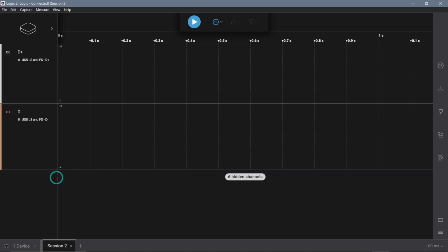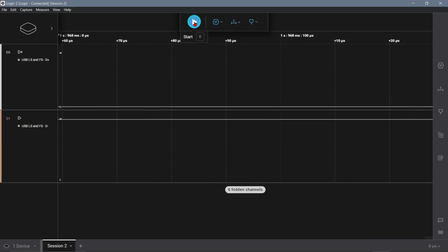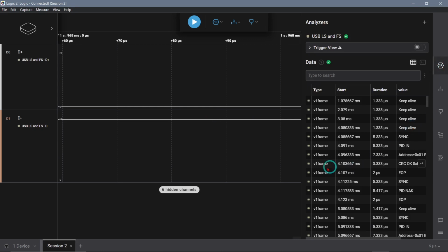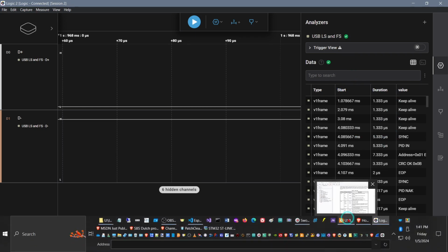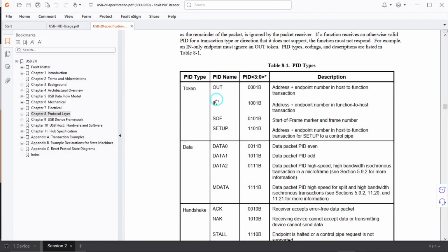And so what we're going to be doing is I'm going to hit the A key, which we know is scan code 4, and I'm going to get it running over here. I'll stop it, and then I will bring in the analyzer window here, and as you can see, there are different packets. These are described in this document over here. There's IN that we are looking for.